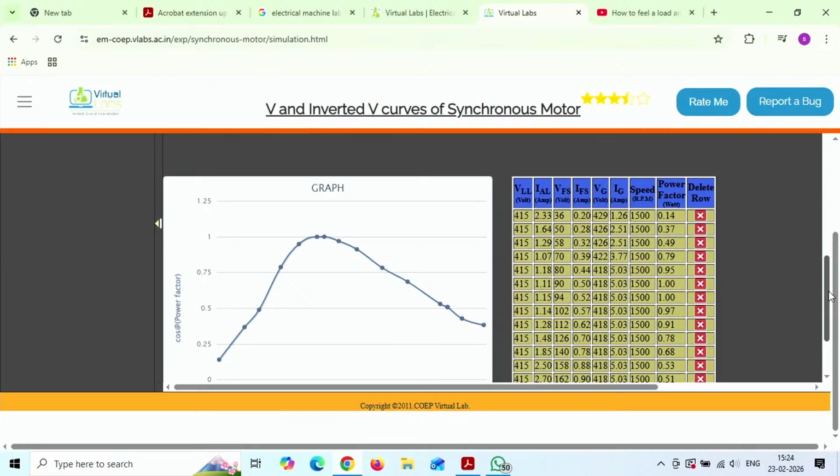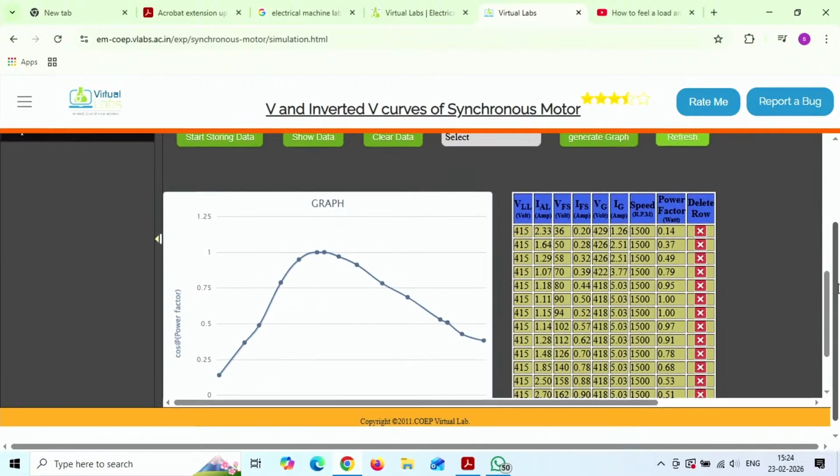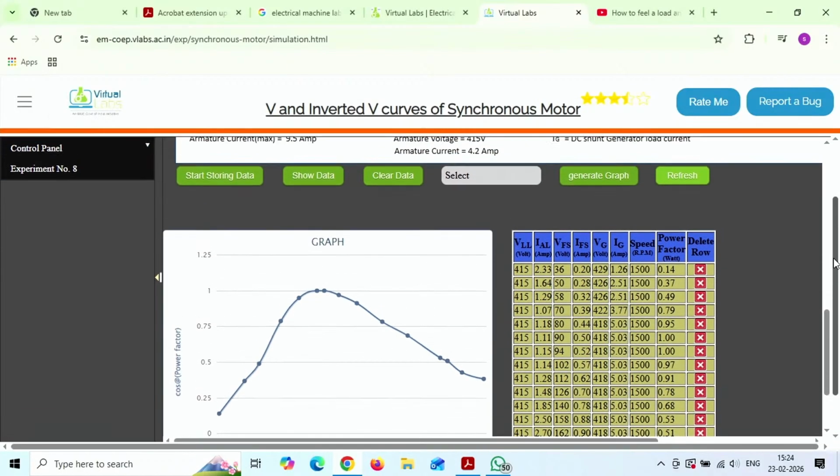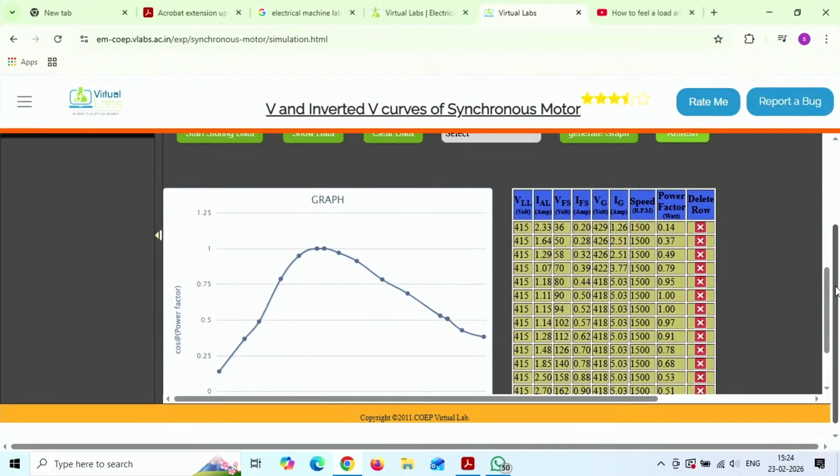In order to model the mechanical load into an electrical parameter, we use the term called slip, during running and during starting. During standstill condition, we have two equivalent circuits, right? But usually we employ the running condition. During running, what would be the equivalent circuit? The rotor now receives S E2, slip times the standstill induced EMF, then R2, X2.